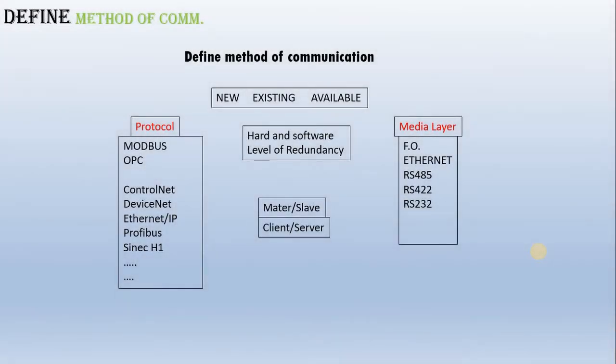How would those two systems communicate with each other? They communicate through a medium, let's say Ethernet or RS485, RS232, fiber optics. This is the pipe which you put your data through. Now the data comes as the protocol you're using. 99% it would be MODBUS. This is the first option for everybody. Everybody now has mainly MODBUS. Other protocols are available.